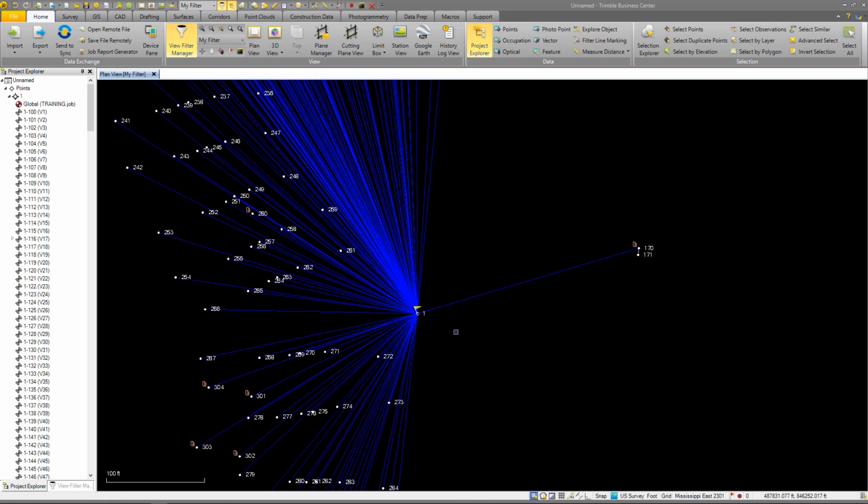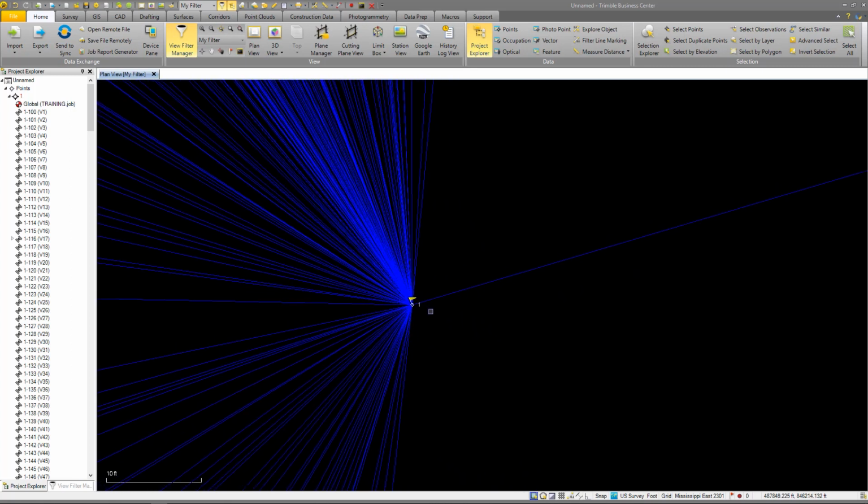So if you look, there's number 1 right there. It knows it's an autonomous position. What I did is just a here position. If I had coordinates, I could have keyed coordinates in and used that. But I did an autonomous position like I didn't have any control set up at all. So I went out there, set that point, logged static data, and then I can correct this based on that static data. I'll get that email in, and I'll show you guys how to do this.